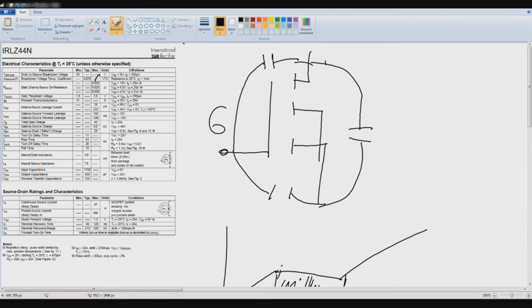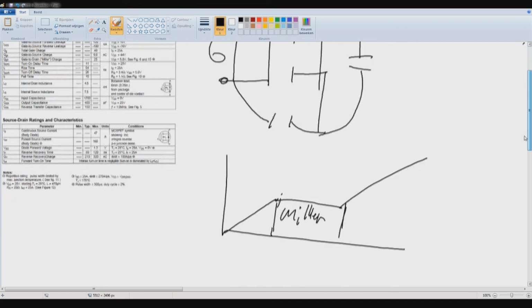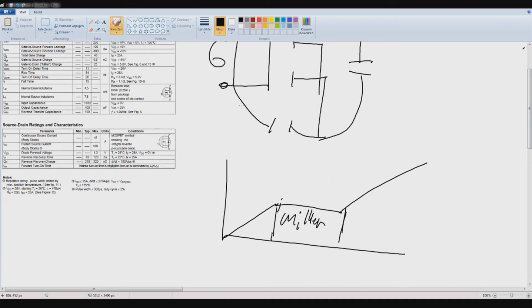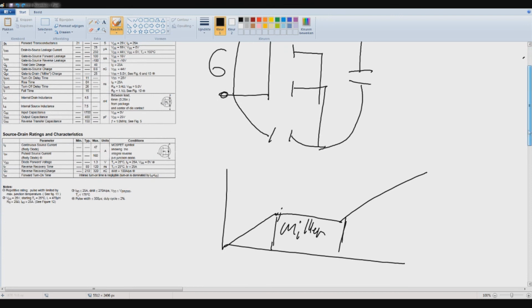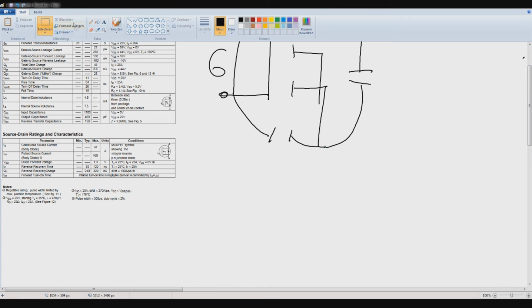And what this can do is introduce switching losses to your circuit, because there is this little period where it does nothing. It's basically charging. And you must keep that in mind with zero voltage switching, ZVS, zero current switching and such.